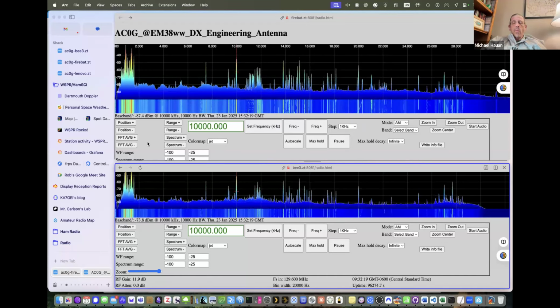I've found that one source of local noise that's fairly easy to mitigate are the tiny switched power supplies that are used to power things like Raspberry Pis, network switches, and things like that. If you can't actually switch them to a true DC source like a battery, in one case, with a Raspberry Pi switched power supply that I was using, I just wrapped it in a bunch of turns of a toroid because I didn't have a DC source immediately available, and that seemed to mitigate the noise.